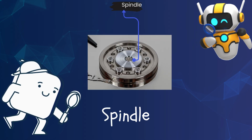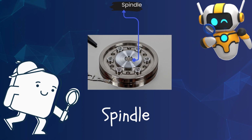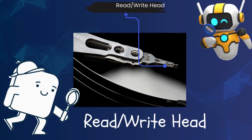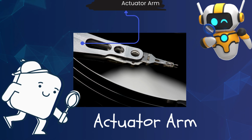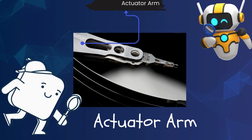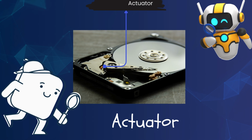Spindle is the axis that holds and spins the platter at high speeds, typically 5400 to 7200 rpm, though some high performance drives can spin at 15,000 rpm. Read write head is the tiny magnetic sensor that reads and writes data to the platters. Each platter surface typically has its own read write head. Actuator arm moves the read write heads across the platters to the correct location to read or write data. Actuator is the motor that moves the actuator arm to position the read write heads precisely.